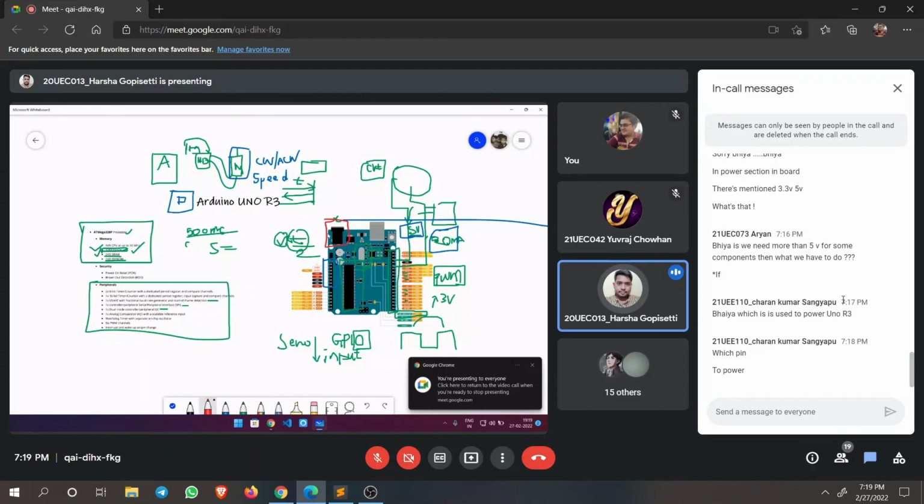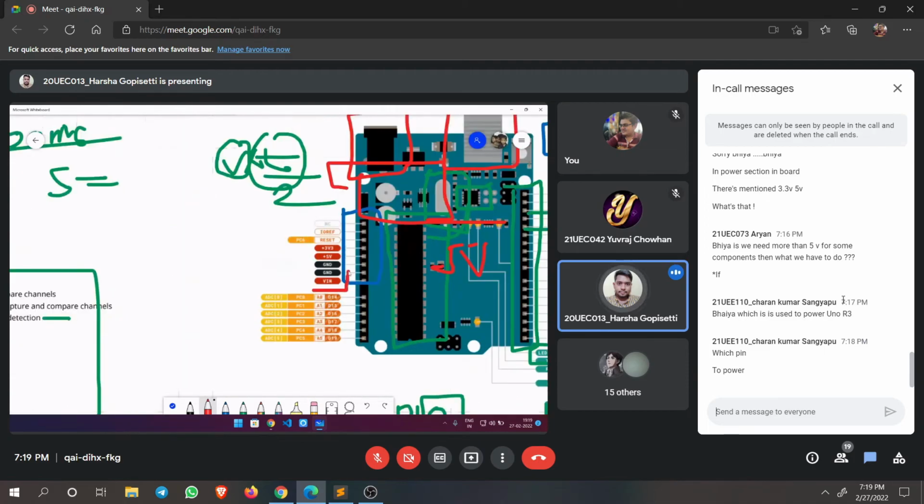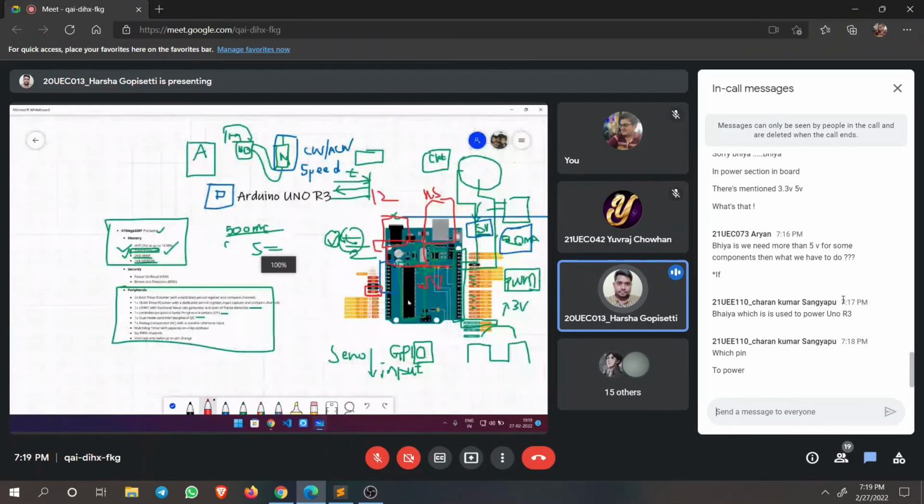As Arduino can be powered using three ways, we can use this 12 volt input, which will be reduced to 5 volt for powering. It will have some circuits here which convert it into 5 volt power. We can use this USB port to power, and we can even use these pins to power. It will be based on your application. Maximum of the times we will be using our laptop USB port.